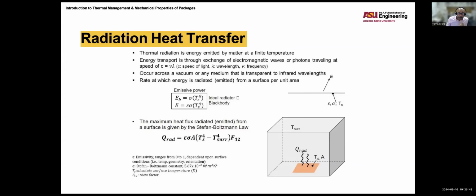So we're actually flowing liquid so that we can control the temperature. Because when you're heating it up, you don't want runaway, so you have to be able to hold that temperature. So sometimes while you're heating it, you have to add a little cooling to keep the temperature constant.